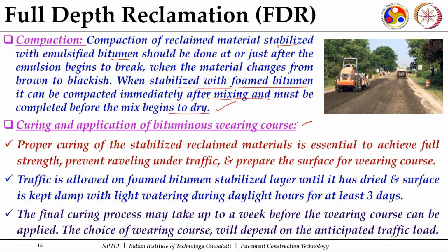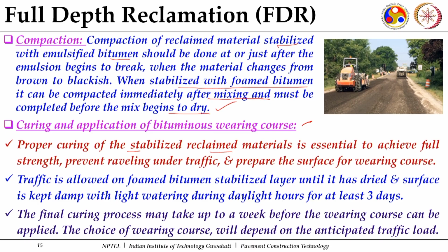So, curing and application of the bituminous wearing course. As there may be various additives like lime or cement added, these additives may require some additional curing time. That needs to be ensured before the layer is opened up to traffic. Proper curing of the stabilized reclaimed materials is essential to achieve the desired strength and prevent raveling. If traffic is opened before curing, then raveling will take place, and therefore, finally, we allow the traffic once the wearing course is laid.